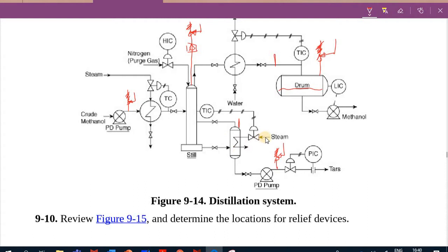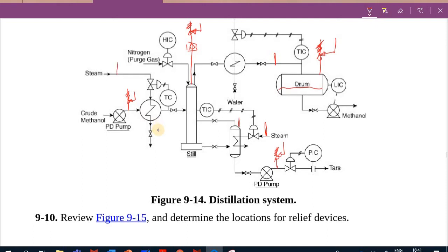considering other things that are totally normal. So I could have some problem on the steam line with a higher pressure coming in, so I can put also a relief valve that could be here, okay. So you can see that I'm adding my relief valves all over the place, the places that I think that I have overpressure. And then I can talk about scenarios.